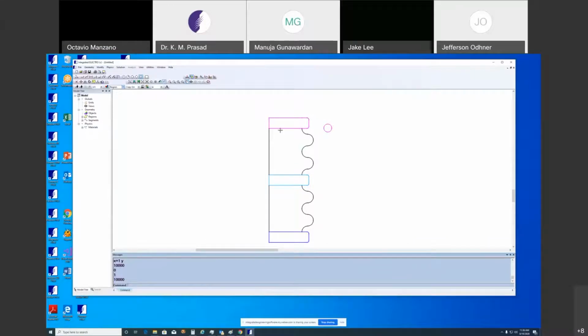We assign only voltage, and the program calculates the equivalent charge that supports the boundary conditions. So in 2D problems, whatever positive charge is here, the equivalent negative charge will be on your lower voltage conductor. This is automatic, whereas in the rotationally symmetric case, it is not. You get an option.